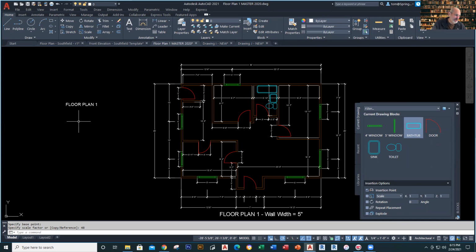You can make it larger or smaller, but use the scale command. Need to make something bigger? Use the scale command. Need to move something? Use the move command. Need to copy something? Use the copy command. Need to rotate something? Use the rotate command. Now that you're learning these things, you're just going to need to lean on what you've learned and get a little more confident with it.